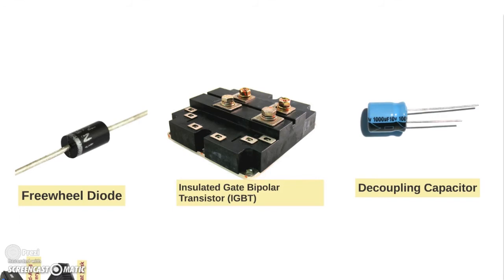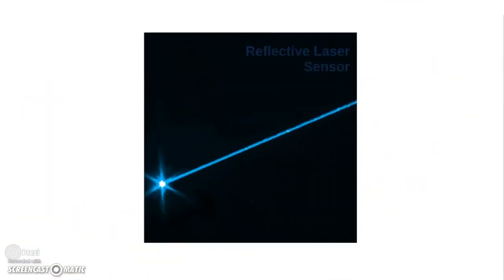Many sensors are installed in order to provide necessary control loop input as well as to monitor performance data such as electric machine voltage and current, in addition to temperatures of key components among others. The reflective laser sensor is one of the critical sensors aimed at measuring the turbine shaft speed. This sensor was the most convenient option, although it had limitations such as the tendency to generate short output pulses under inappropriate conditions.